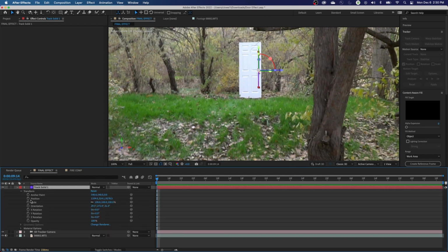I'm going to go to Transform, and go to the Y-axis rotation, because the Y-axis is moving up and down here. The X-axis is pointing straight toward us, and the Z-axis, which is depth, is pointing to the right now. I was wrong, it's not pointing to the left, it's pointing to the right. So we're going to rotate it around the Y-axis and make this square face toward us.